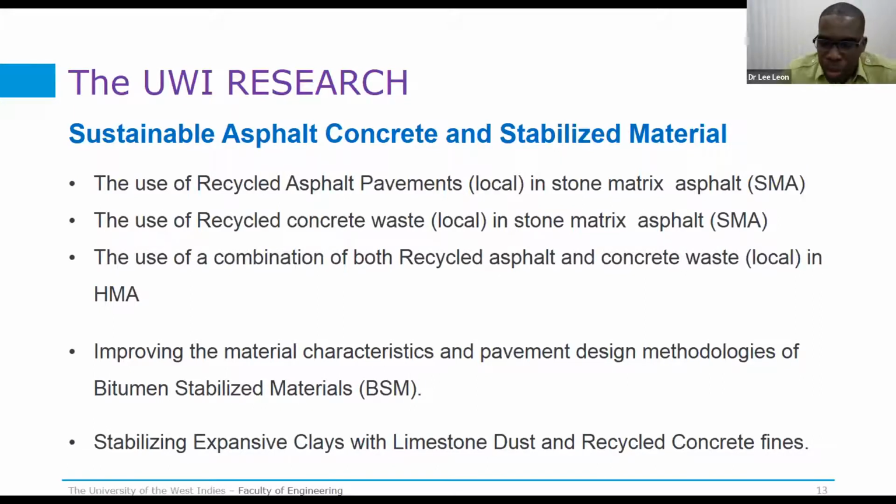This will reduce the cost because you will reduce the percentage of virgin aggregate you have to use. And improving the characteristics of bitumen stabilized material, and also stabilizing clay, expansive soils with limestone dust and recycled concrete fines.